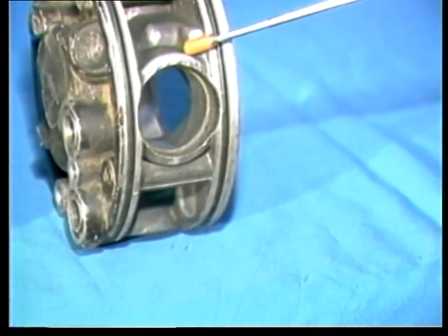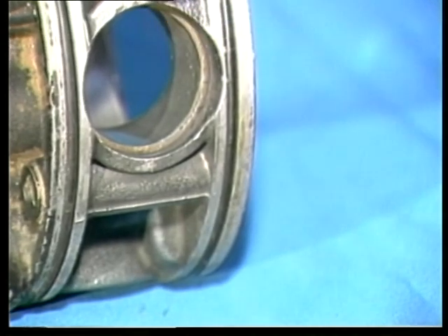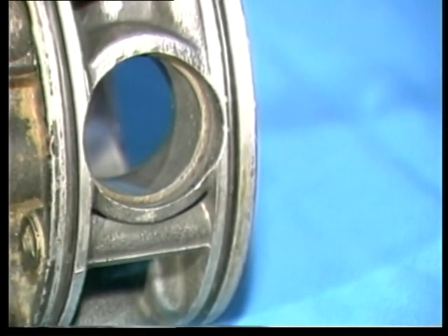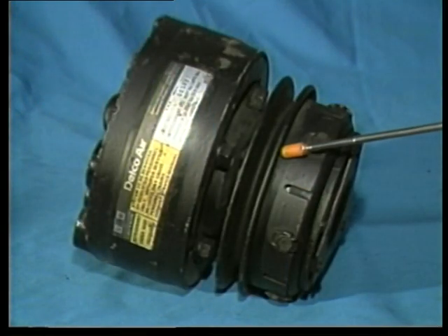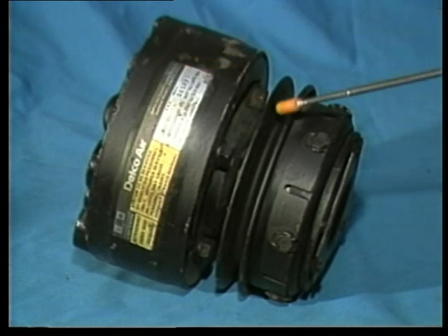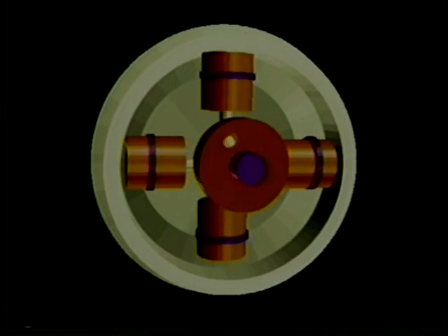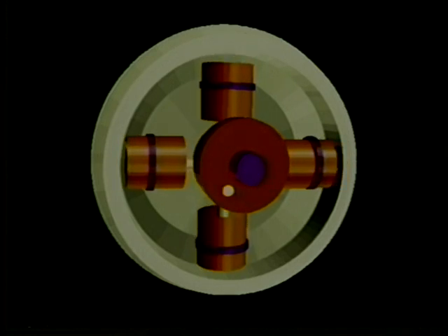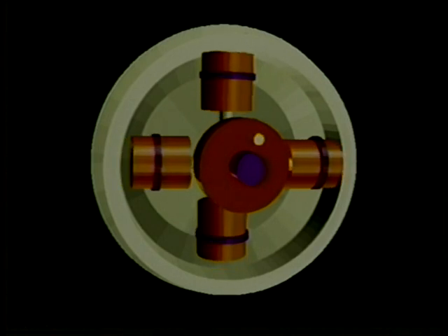The cylinder block provides bores for the pistons and also houses the discharge reed valves. A large metal ring fits around the block and seals against large O-rings. This is a lightweight, compact compressor design. Here you can see the basic motion inside a radial compressor. The pistons move in and out around a central crankshaft axis.